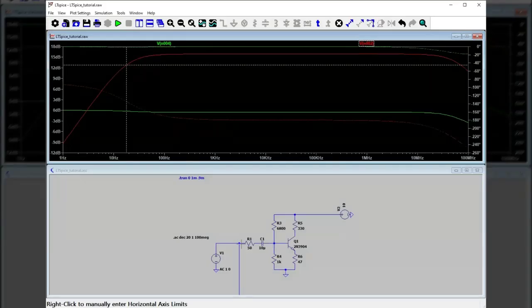Actually, you use 850 ohms, this 50 plus that, and calculate the RC high pass corner frequency, and you'll get around 18 hertz, which is verified here by LTspice. All right, and this is the AC analysis that we're doing. What about on the high side?